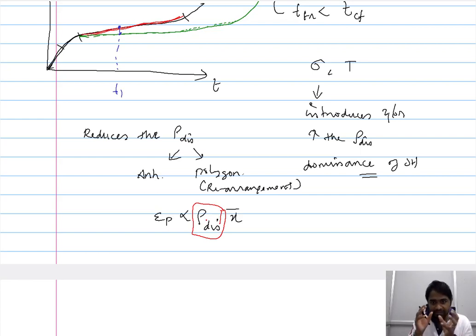However, there are some dislocations that are still available, and these dislocations contribute to the plastic deformation through their mobility. So these dislocations that did not annihilate or rearrange still propagate, they still move, and the increase in the average distance covered by the dislocation that has not been consumed by annihilation or polygonization contributes to the observed strain in the steady state condition.